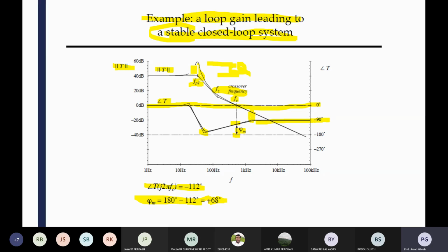If the peak is less, then you can see there is some overshoot change in your physical system. Overshoot change means when you are checking the reference tracking of the converter, you can observe that the response has less overshoot. Are you getting my point? Reference tracking: your reference Vref is there, you are adding some step disturbance to your reference, means you are adding an additional step voltage with your reference voltage. So as if your converter is working properly, regulated, and it is working in the steady state.